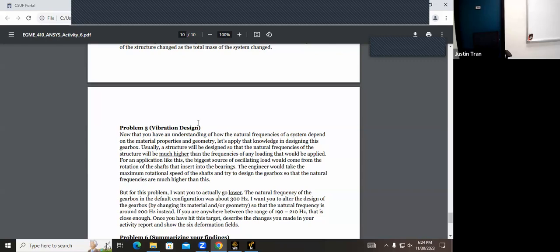So for the minimum for the conversion step, I would like to see maybe at least 4 different meshes. You can start with something as coarse as you can go without it breaking. And you don't have to do the conversion step on every configuration. Just do it for one. If you're having trouble getting more elements on it, try it on these computers, because these computers have a little bit of a better version. I think these ones can go up to, whereas the one that you download from the website, I think it was up to 64,000. You may have more luck getting the conversion. But it's great. This looks really good.